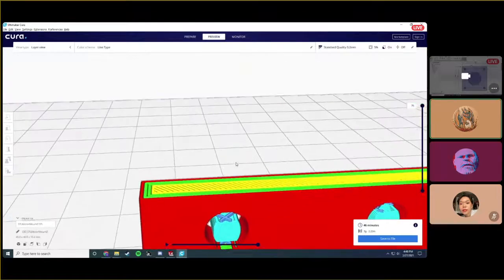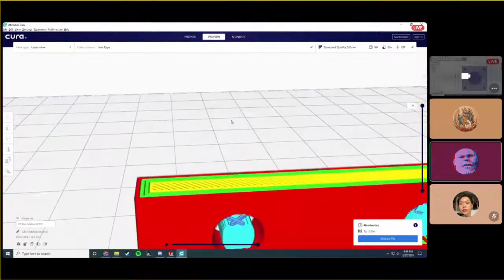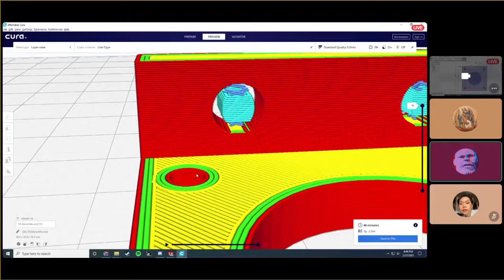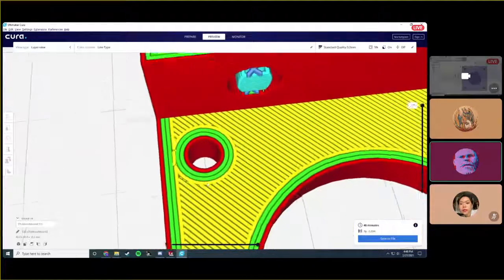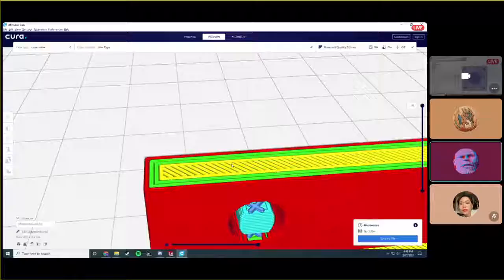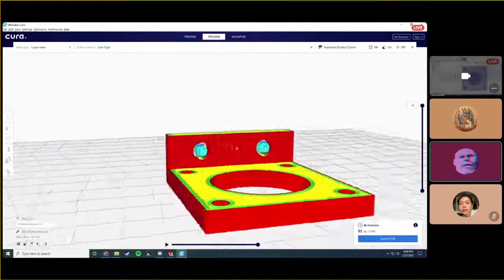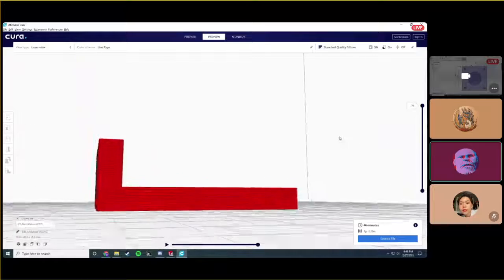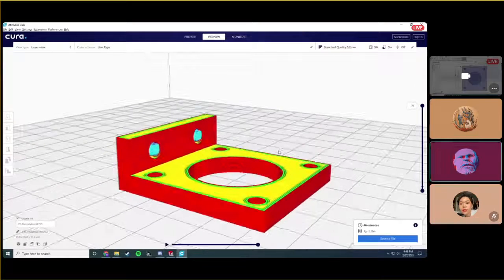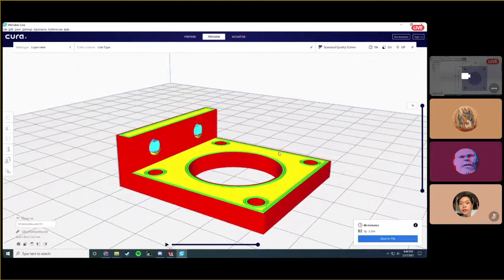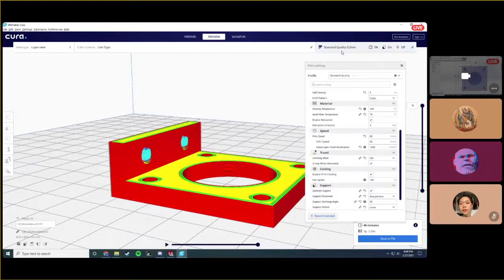Yeah, you can kind of tell. And you can adjust that too if you want a more accurate model with more curvature everywhere. You can adjust the layer quality, the standard quality, it's each layer height. So if you were to reslice it at like 0.05 millimeter layer height, it would be a better circle. Yeah, I guess I can do that. Why not?